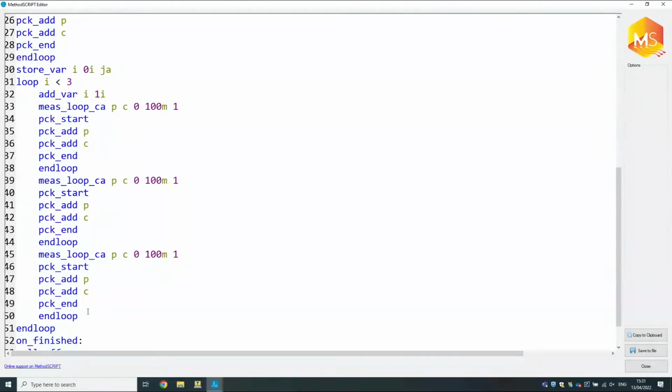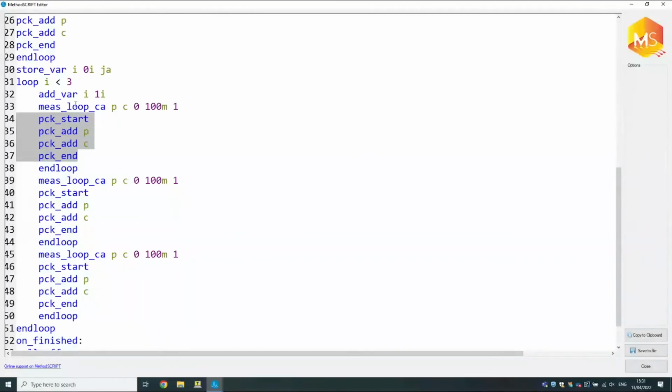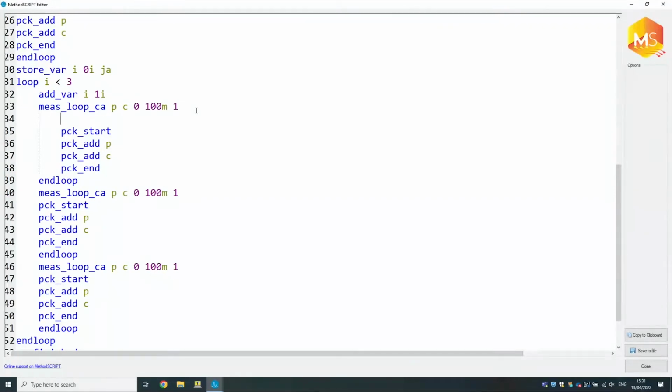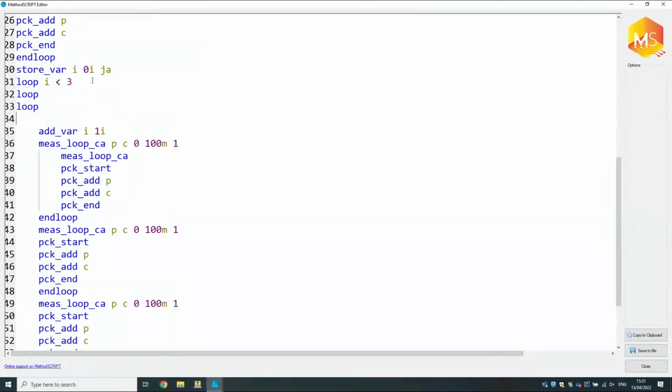Yeah, that's great. And now the difficult question, can you do a loop in a loop? Yes, in fact, it's kind of already what you're doing, because a measurement loop is also a loop. It's just you can't do 2 measurement loops in each other, so you can't say do 1 measurement loop here and then say inside of that do another one. That's not allowed. But if you use the simple loop command, you can chain them however many times you like.